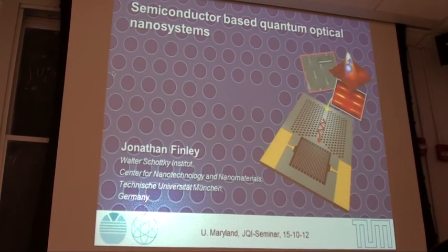And the vision for the work we're doing, and I'll try to illustrate this in my talk today, is really to move towards a scenario where you can essentially have qubits on a chip. You can have them exchanging photons, which are guided via photonic crystal waveguides. And also then, as I'll show you today, we've very recently made superconducting single photon detectors, which are already on the chip and actually can detect single photons with a pretty high 20% efficiency on gallium arsenide. So these are the kinds of topics I'm going to try to discuss today.